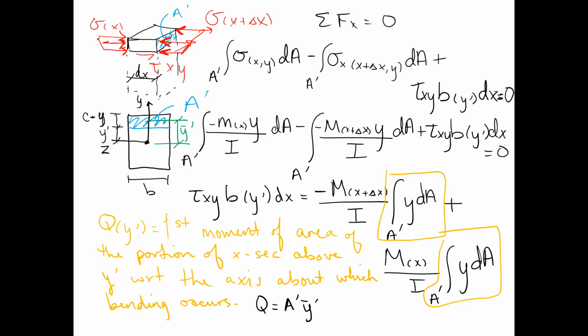All right, so there's a couple locations where we can look at this and know what the value of Q is. Okay, so if this is our cross-section, considering that formula I just gave you, what is the value of Q at the very top? 0, and why do you say 0? There's no area above that. Good. So here, Q equals 0.